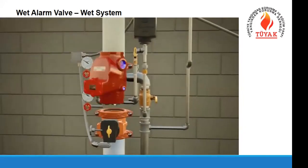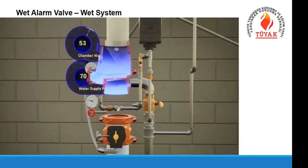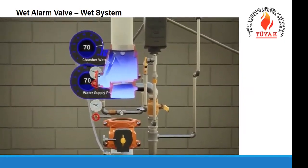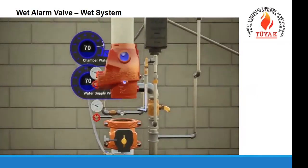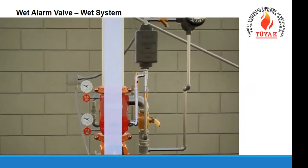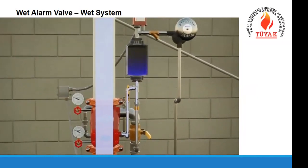After the sprinkler activates and water flow is established, the clapper is fully lifted off of the seat and the alarm ports are exposed, allowing water to enter and fill the alarm line. If the system is equipped with a retard chamber, there will be a slight delay as the chamber fills before activating the water flow alarm.